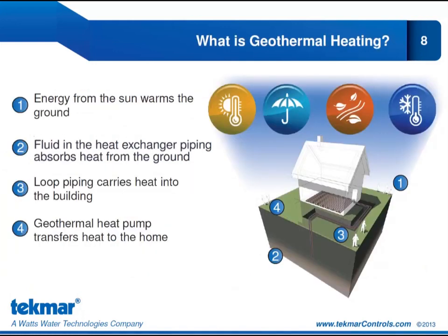Now, what is geothermal heating? Well, geothermal heating uses the earth or water as its source for energy, and it takes low temperature heat from the ground and concentrates it using a heat pump for distribution to a load. Typically, we are looking at entering temperatures of about 50 degrees Fahrenheit, and we are able to boost that temperature all the way up to 120 degrees Fahrenheit for our load side demands.